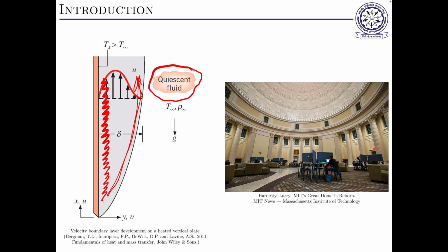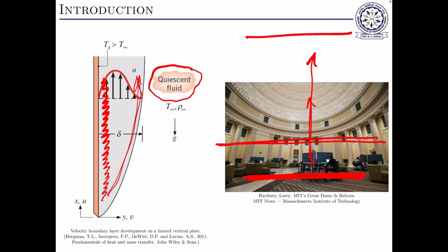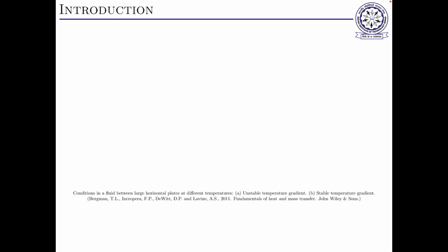So if people are sitting on the ground floor or at the bottom, because so much height is there, natural convection happens. Although natural convection would also have happened in a small cubicle, because here the height is very high, natural convection is more effective, so cooling happens in a better way, and without any AC you are getting a better ambience inside. So this was the technology of the olden days. No compressor, nothing is required. Simply using the property of fluid, we are generating a cooled environment.